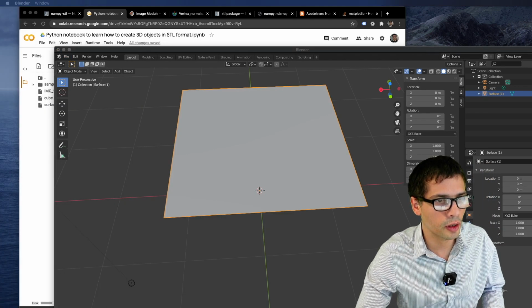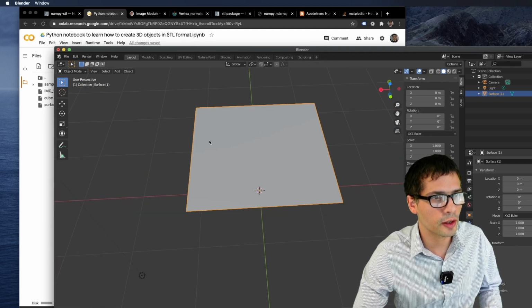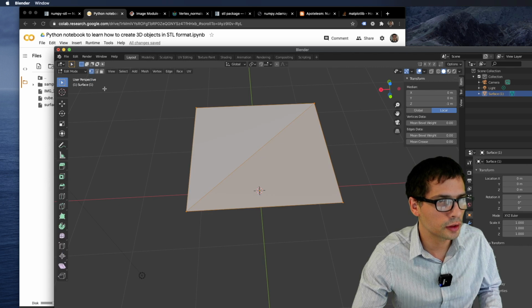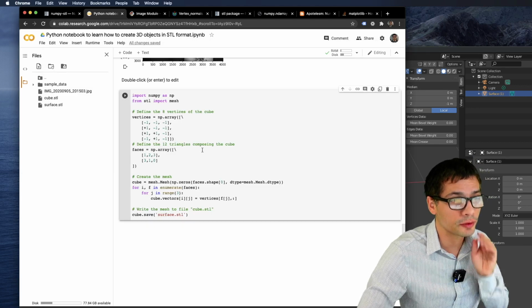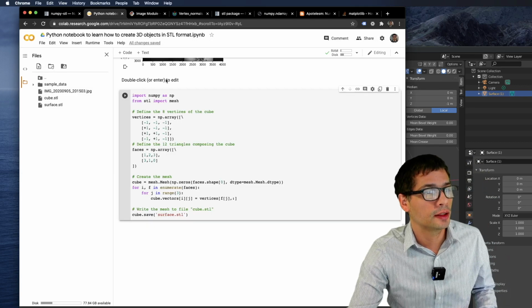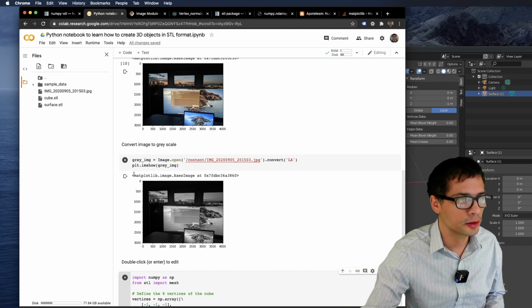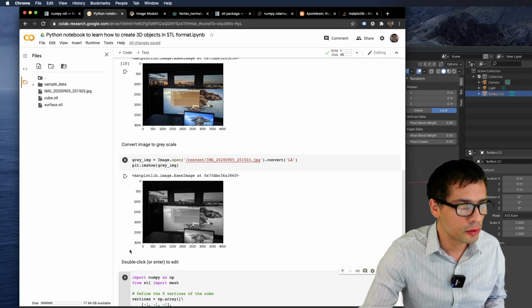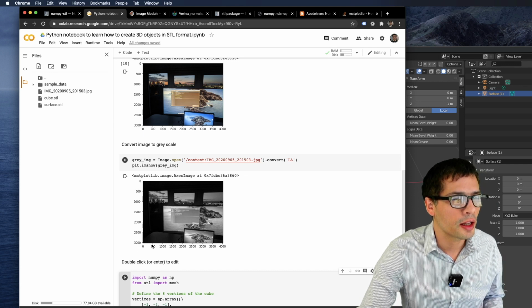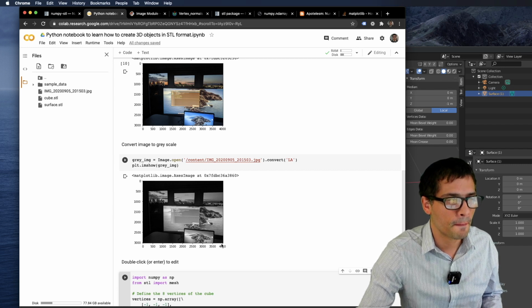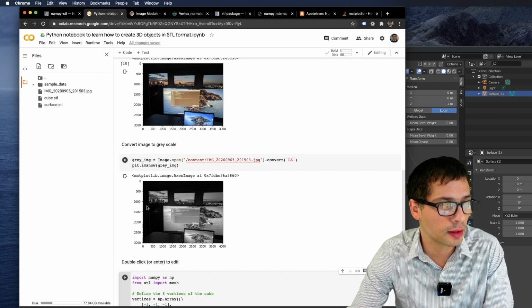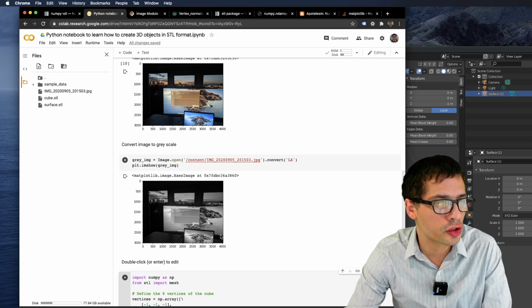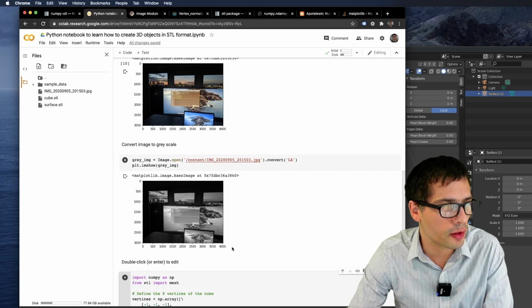Okay, so now it looks good, right? So this is a surface. It looks like a square, but when you look into the vertices, we have like 2 triangles. I have an image of what resolution? Let's see. I'm working everything out. Okay, so this image has 0 to 3000 and then 0 to 4000. If I wanted to be very very detailed in my lithograph, I would create an impossibly large mesh of 3000 times 4000 vertices.